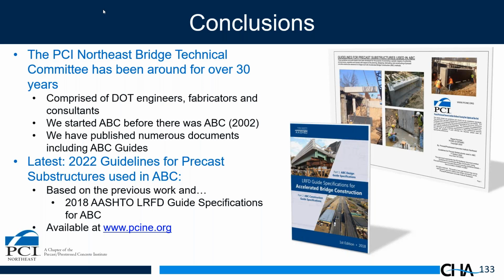We haven't seen that yet because prefabrication has not gotten that popular. But to try to standardize things, it's very difficult to come up with standardized cross sections that would justify the manufacturing of steel forms. So for the most part, we're seeing wood forms used at this time in the industry. Yeah, okay. The standardization would be difficult. It's just that every bridge tends to be unique unless you can actually come up with a design that could be repeated at several locations, which typically does not happen. So that's why the standardization of the elements is difficult.